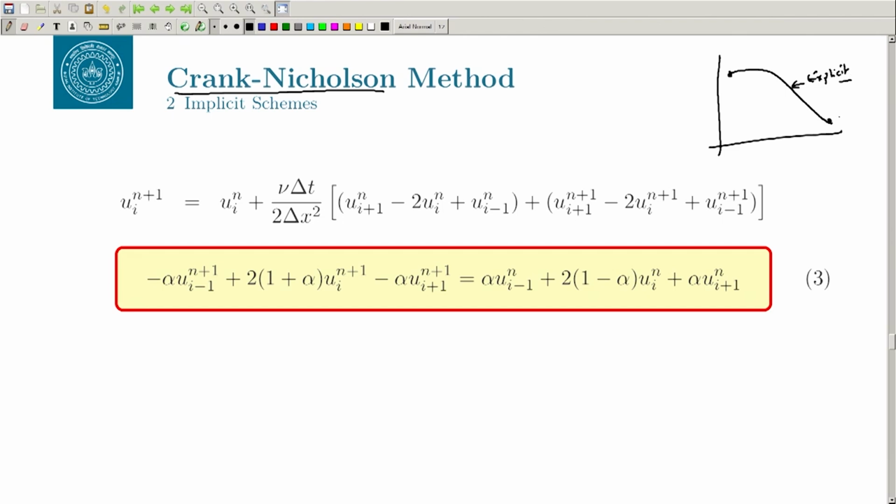But in the case of RANS simulation, this is, let us say, your number of iterations. Okay. So, your interest is basically to get the final solution regardless of the way you choose. Okay. So, if you can get an approach which can give you this convergence very fast by increasing the delta t, and of course the intermediate solutions are not correct, but you are getting the final solution which is the same as the solution you would get from the explicit approach. So, then you are saving a lot of computational time. Okay. So, this is only possible when you use the implicit time stepping.